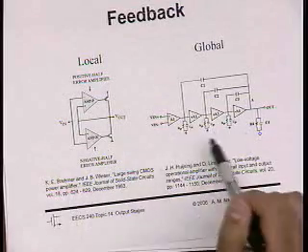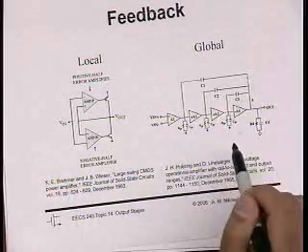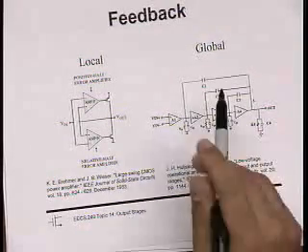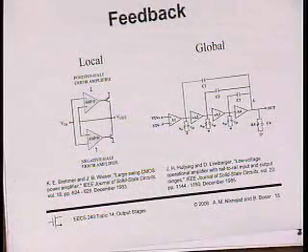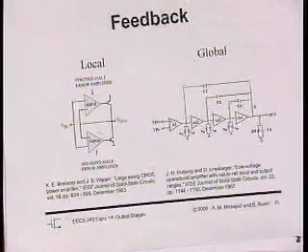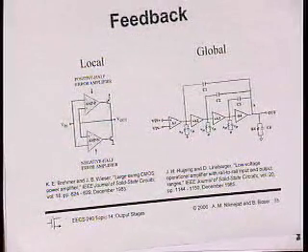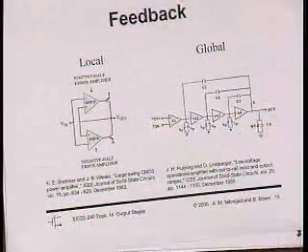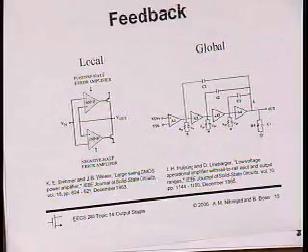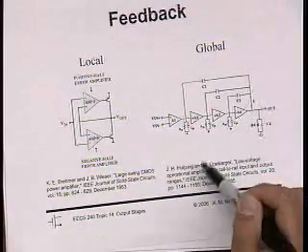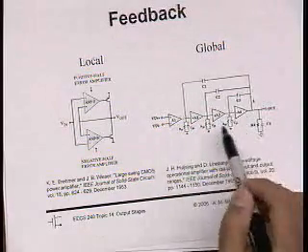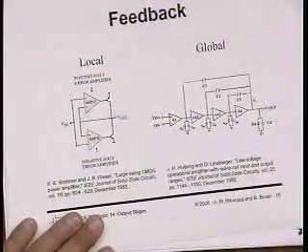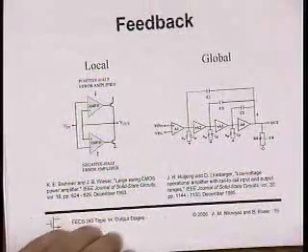The other approach of designing an output stage is if your output stage, in fact, is producing a pole which is, let's say, significant, not beyond the unity gain frequency, then you really have to take it into account. And for instance, you may end up with 3 or 4 gain stages. And so then we'll briefly look at Miller compensation, nested Miller compensation, in order to deal with the multiple poles and zeros that you get in that situation. Okay. So let's first start out with this idea of a helper amplifier.